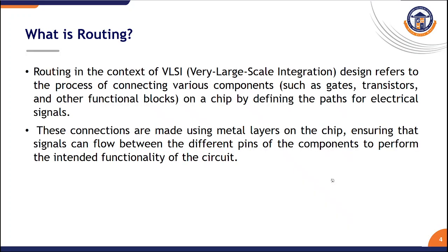And the next one is, what is routing? Routing, in the context of VLSI design, refers to the process of connecting various components such as gates, transistors, and other functional blocks on the chip by defining the path for electrical signals. These connections are made using metal wires on the chip, ensuring that the signal can flow between different pins of the components to perform the intended functionality of the circuit.